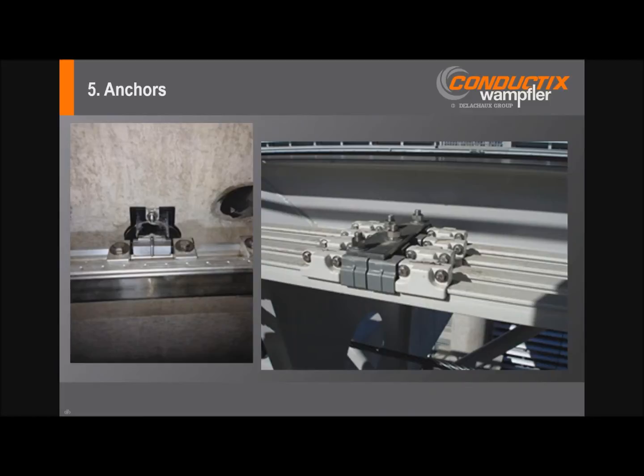Anchors essentially serve to secure the conductors to the hanger at specified intervals. So think of these spaced in between each of the expansions, midway. Expansion spacing may be 80 to 200 meters depending on the temperature, the size of the conductor, the ambient and current heating. These anchors may be either a friction clamp or through-bolted design, but they must be able to withstand the force of the collectors under expansion and contraction as they counteract the force of the conductor sliding through the hangers.